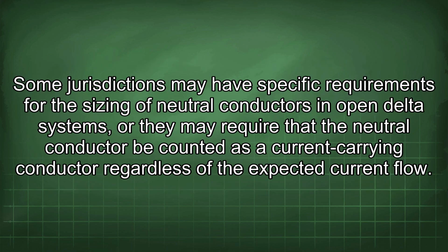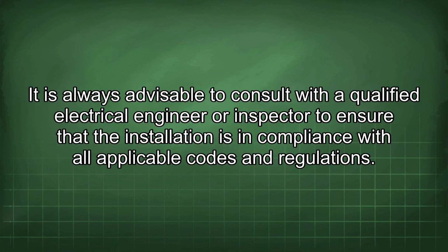Some jurisdictions may have specific requirements for the sizing of neutral conductors in open delta systems, or they may require that the neutral conductor be counted as a current carrying conductor regardless of the expected current flow. It is always advisable to consult with a qualified electrical engineer or inspector to ensure that the installation is in compliance with all applicable codes and regulations.